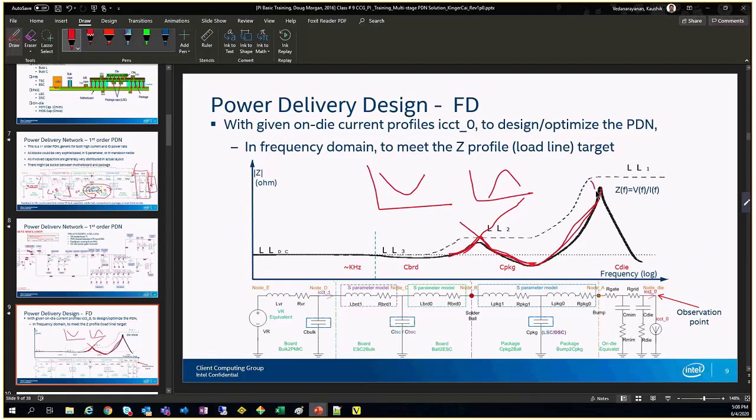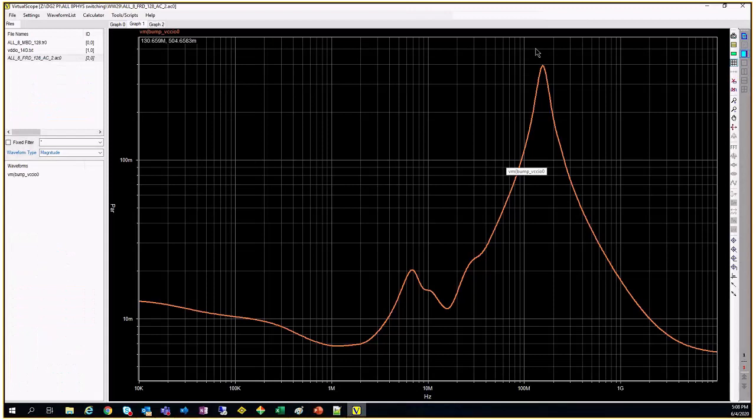After that, the impedance is brought down by the die capacitance after one frequency, because the die capacitance is such a small value, like picofarad and nanofarad, no? They can only act at a very high frequency. In my case, the die effect is only coming up to 200 megahertz, almost 150 megahertz. Then the impedance is coming down. If you see the effect, it's bringing it down so high. From 150, it's bringing it down to such a low value, right? So this is the impact of the die.